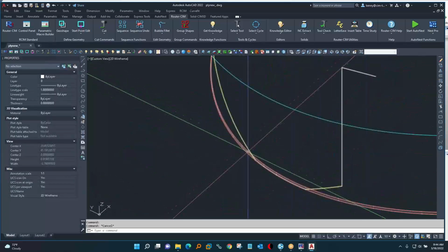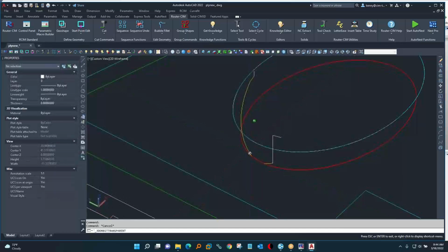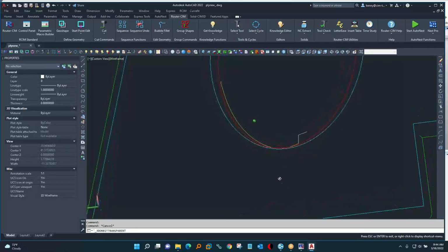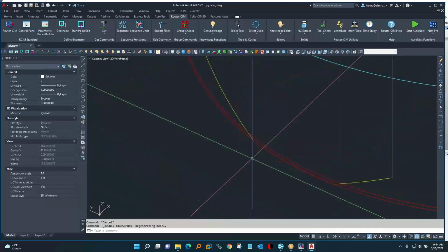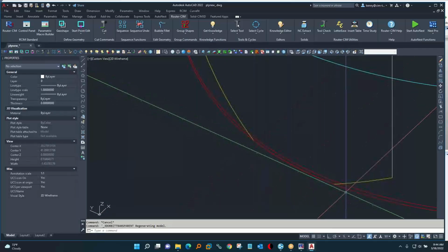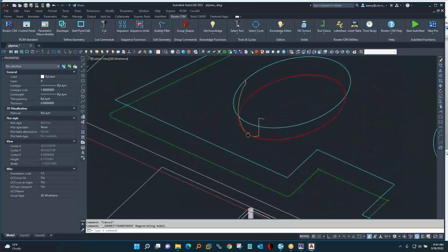So this is 2 passes. It ramps down right along the contour of the shape. RouterSim's the only one making a helical move like that, follows the contour of the shape, gets to the first level, cuts around the part, slides down to the second level, overlaps, leads out, cancels cutter comp.